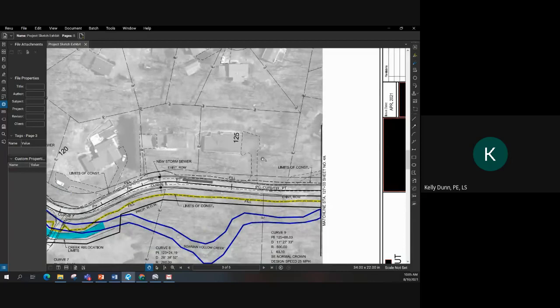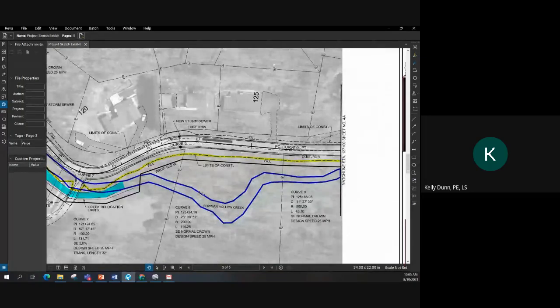However, the east side of the roadway, if you recall, is bordered by a hillside, and the west side is bordered by a fill slope. Due to this, significantly more runoff could be expected to fill the gutter along the east side of the roadway, because it's going to run down the hillside, come across the shoulder, and pour into the gutter pan. That won't occur on the west side, because there's no off-site flow really coming to the gutter pan.